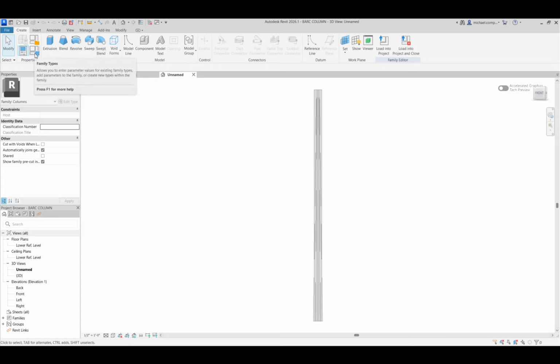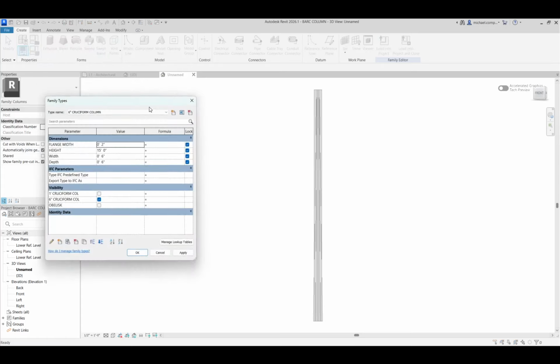So I'm actually going to name them that. So before I go any further, because they're all going to have visibility toggles, I'm going to create one called Revolve. I'm going to create one called Sweep. And I'm going to create one called Sweep Blend. Okay. And then similarly, I'm going to create new visibility parameters for all 3 and then assign them as they model them.